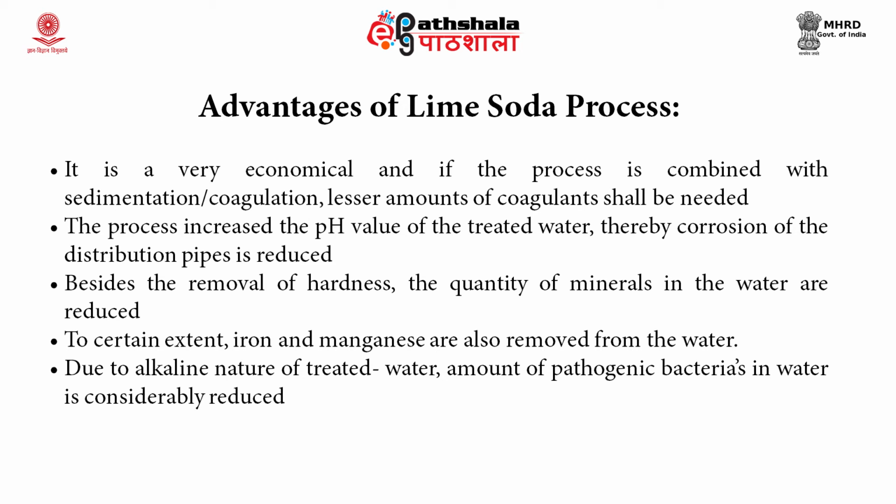This lime soda process is a very economical process, and if it is combined with sedimentation or coagulation, lesser amounts of coagulants shall be needed. Further, the process increases the pH value of the treated water, thereby reducing corrosion of the distribution pipes. Besides removing the hardness, the quantity of minerals in the water is also reduced.